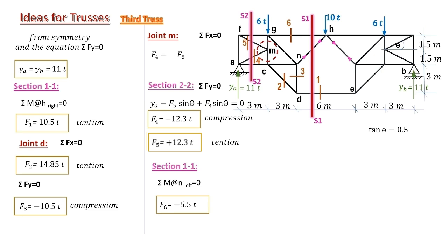Or as we previously said, we can compute NH first considering the Y direction in section S1, S1. Then we will have one unknown, which is member 6, when we consider our X direction. We assure that there is no one solution for the members. There is one final answer, but several engineers can proceed with several procedures.